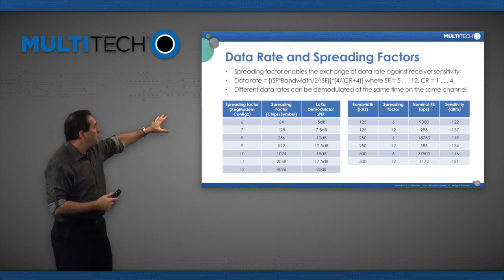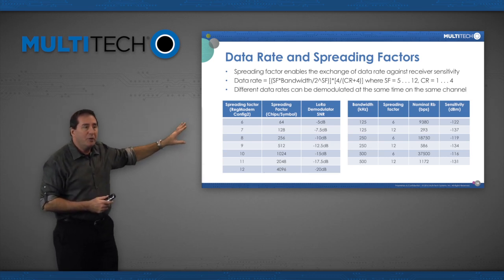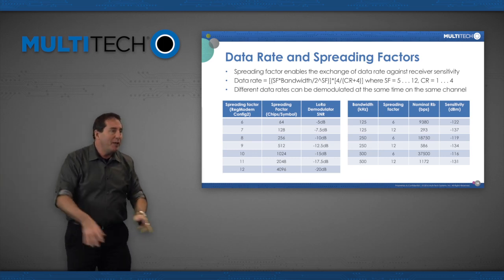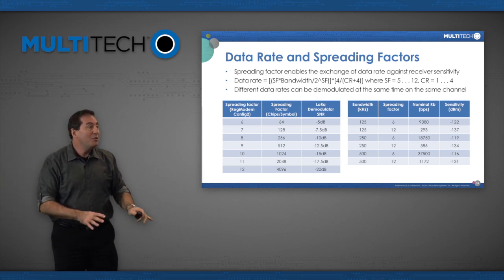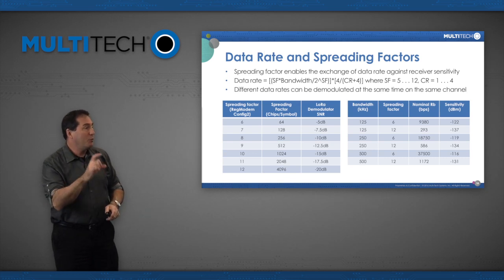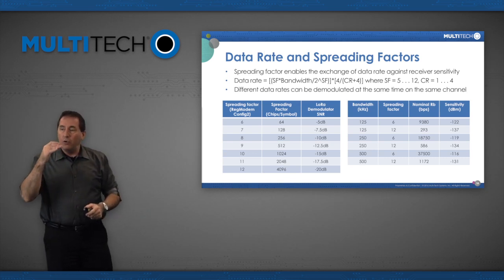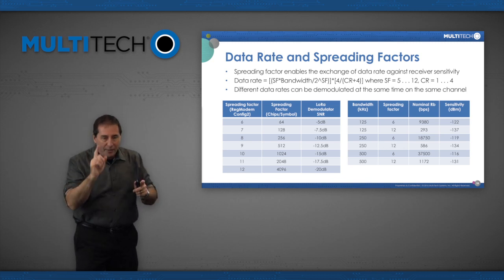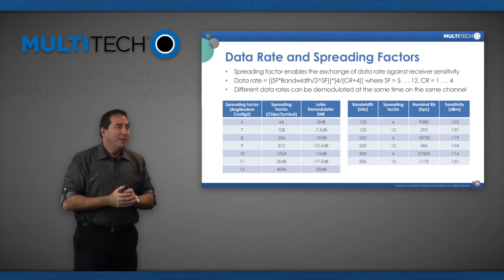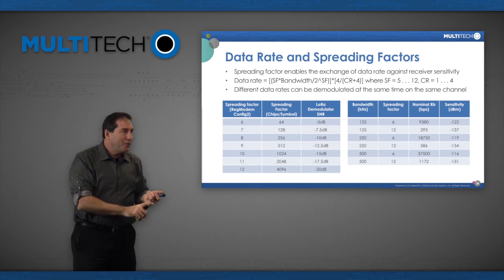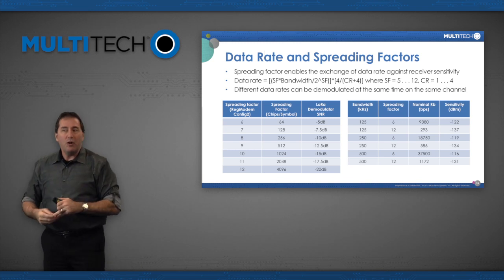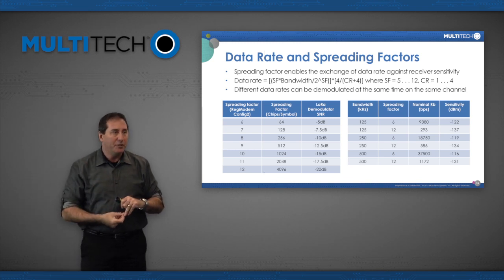So we've tried to make this simple in LoRaWAN and kind of hide this spreading factor and bandwidth, relatively confusing thing, under a thing called a data rate. And in the LoRaWAN protocol, there are specified data rates. I'm going to work at this many bits per second. And if you know that, you know what your spreading factor needs to be, and you know what your bandwidth needs to be. Have I confused you all sufficiently? I can make it more confusing. Okay.